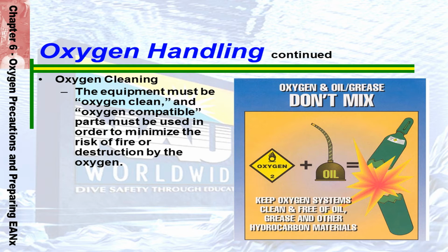This special oxygen cleaning can be complex, involving an initial cleaning using solvents that removes all hydrocarbons, and then the use of special oxygen-compatible lubricants, O-rings, seats, seals, flexible tubing, etc., as the system is reassembled. Even though certain materials may not be flammable in the presence of high-pressure oxygen, more durable materials that do not so rapidly degrade will be substituted.